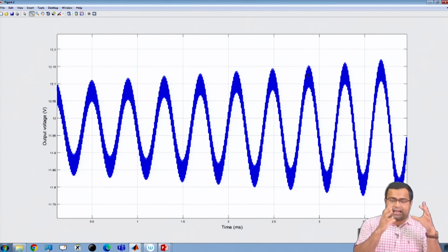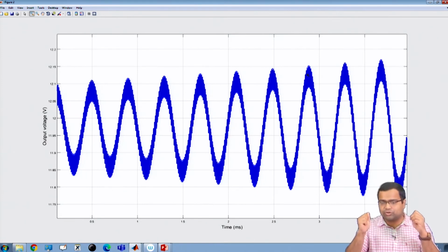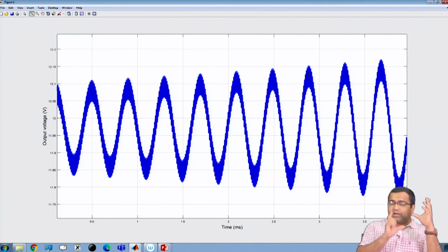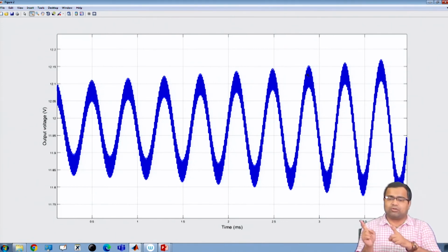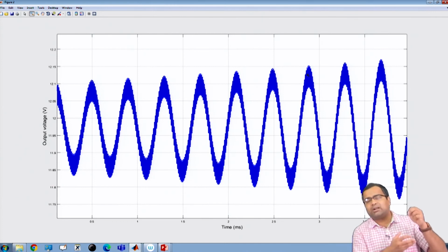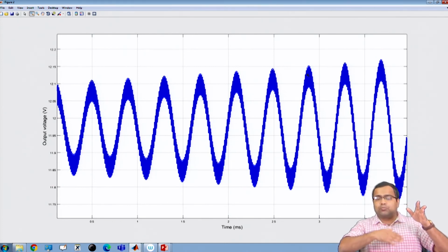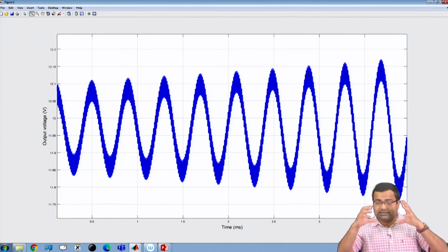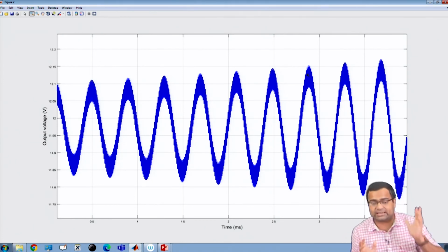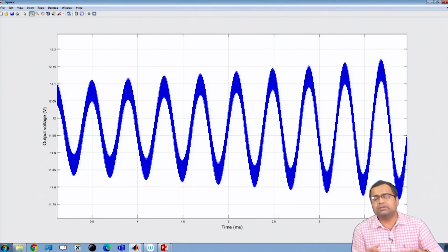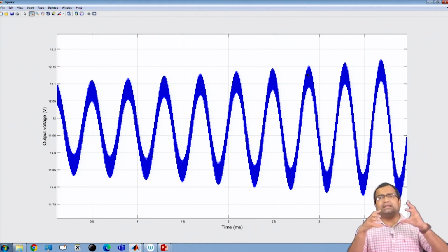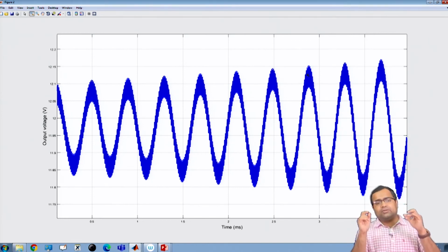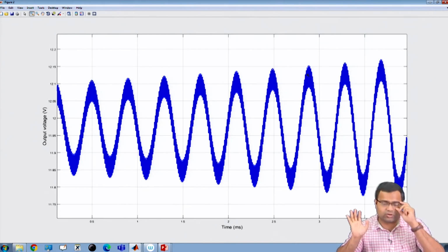Here the IBC is driving a POL converter and the POL converter is tightly regulated using current mode control, and since it resembles to some extent a constant power load, and an open loop buck converter driving a constant power load, when we reduce the intermediate bus capacitor, the open loop converter becomes unstable. As a result the output voltage oscillation amplitude is slowly increasing. Okay, and if you wait for a long time, that oscillation will grow significantly and it can damage the converter and the device, and it can lead to complete collapse of the closed loop two stage converter.